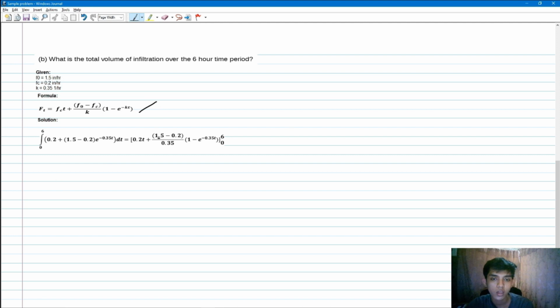And for us to get the total volume of infiltration over the 6-hour time period, we need to subtract the value of F when our time is 6, minus the value of F when our time is 0.